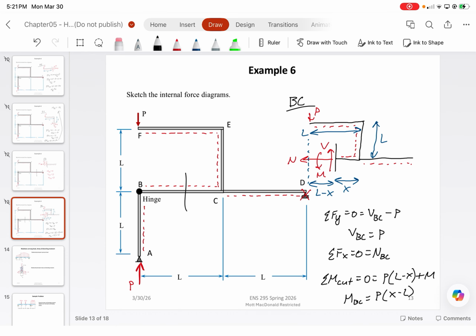So in this case, because the hinge is there, it's basically acting as a pin roller where it allows for free rotation. Any questions so far? The roller connection is the shear. A roller connection would be another type of shear connection where the only translation of shear is vertically, or in whatever direction it's supporting the load. The pin can obviously support shear in both x and y directions. So in this case, a hinge would technically translate forces in x and y. But yeah, it just translates forces, but it allows rotation.